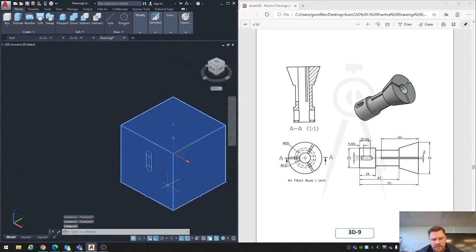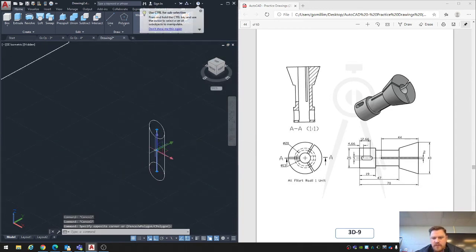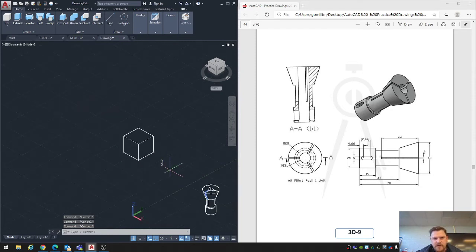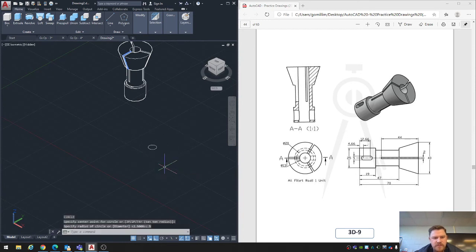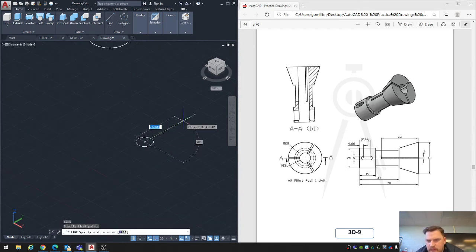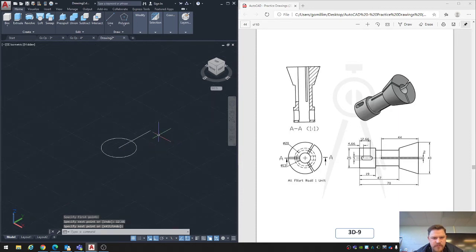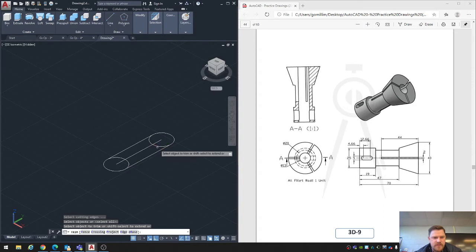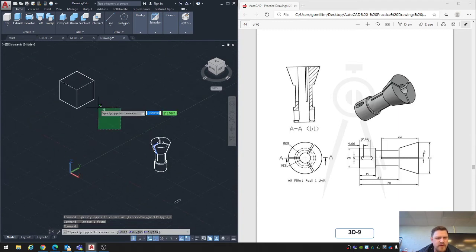Let's erase. I can move this thing out of my way now. I can erase the middle line like that and use trim. Oh no, trim's not working. That's a yikes. What if I do it flat? Circle, diameter 5, line 12.66, circle, diameter 5, line from quadrant to quadrant, trim. So now it lets me trim there for whatever reason. Wouldn't do it on the other face, which is what I need.